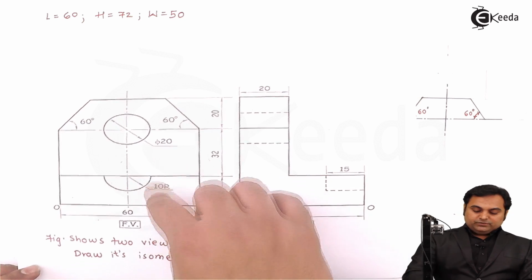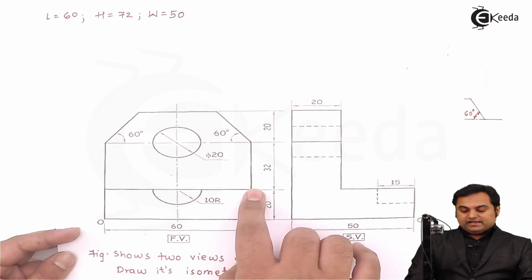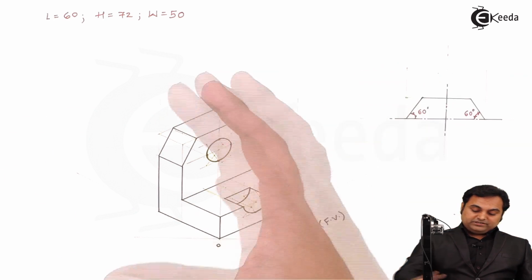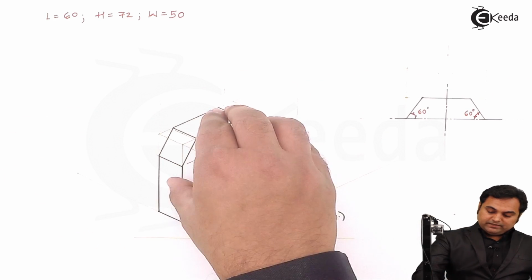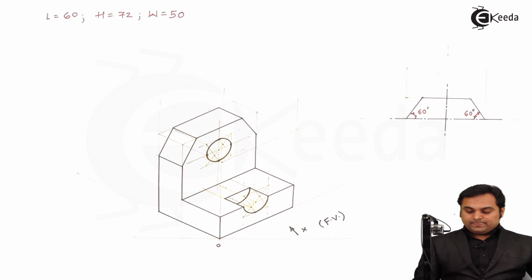Next, between the vertical and horizontal blocks there will be a dark line like in this orthographic drawing that indicates change of plane. So that change of plane I have shown here with the help of this vertical and horizontal surfaces on different planes.